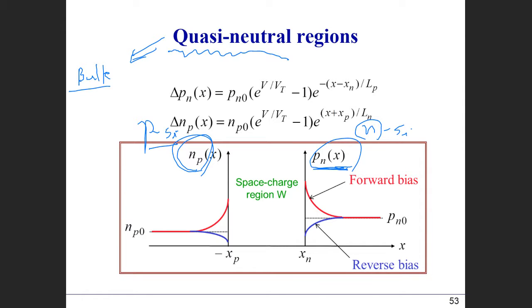And then when you plot this carrier concentration from the thermal equilibrium value, we can have this kind of exponential decay when you apply the forward bias. When you apply the reverse bias, now your carrier concentration is actually lower than your thermal equilibrium value. Then from there you get an increase of this carrier concentration and then reach the thermal equilibrium value.